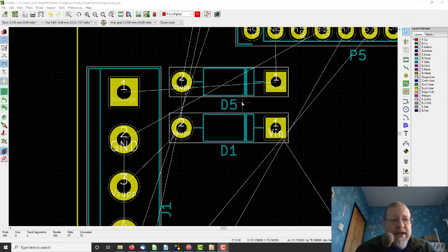Now 6 mil, or 0.15 of a millimetre, a mil being 1/1000th of an inch, is standard for our very cheap prototyping. So as long as we're within that, and that's for spacing and track thickness. Also, our board is carrying, well, not high currents, but significant currents. So we need to have sufficiently thick tracks to carry that current.